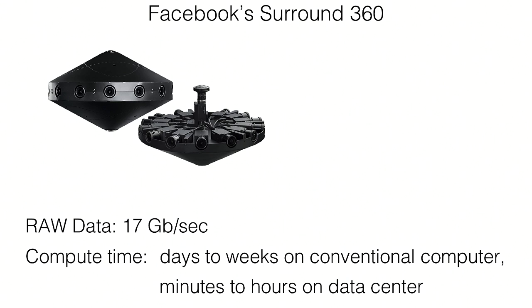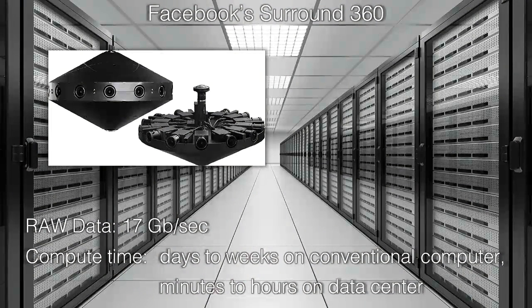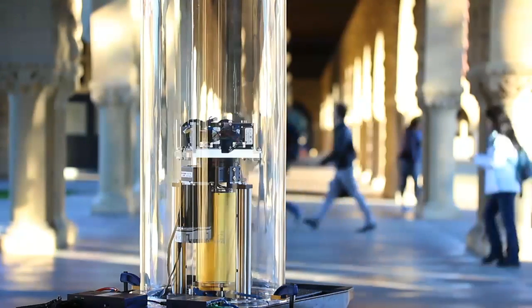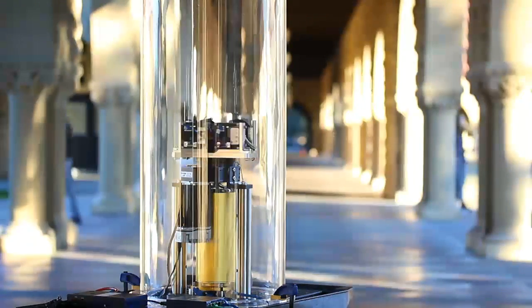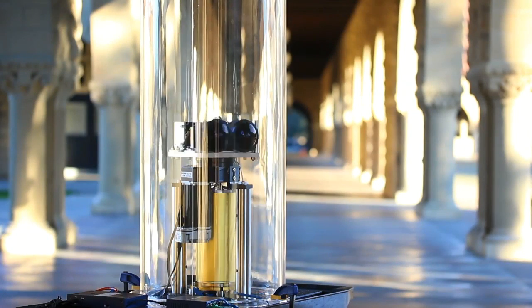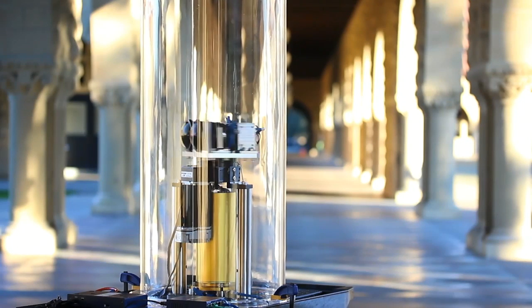So the problem here is that you need a large data center maybe to be able to capture data and then stream it in real time. So we have proposed a slightly different approach to these camera rigs, in that we try to trade off some of the computational complexity for mechanical complexity by taking two slit cameras, essentially taking the idea from the initial Peleg et al. paper and spinning it at very high frame rates.